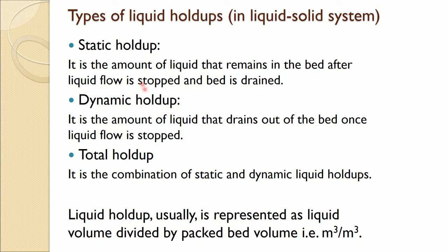So, static holdup is the liquid just staying between the particles after the liquid flow is stopped. Dynamic holdup is a moving liquid through the packed bed. Once you stop the liquid flow, whatever you collect is known as the dynamic holdup, and the total holdup is the addition of these two, static and dynamic liquid holdup.